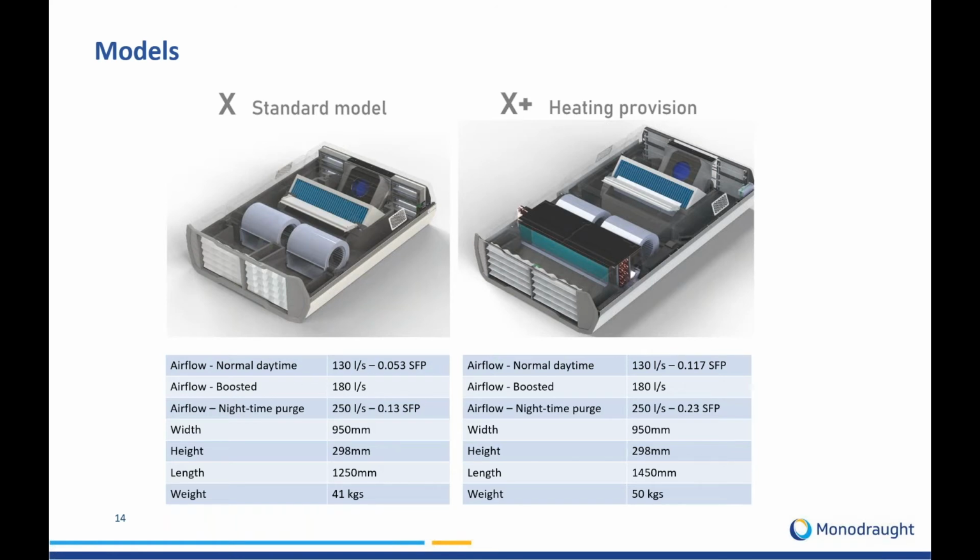The calculations are there, but not quite. So worst case scenario, we just said, let's incorporate an extract fan from day one. The fan with the black square with the blue circle in the middle, that is the extract fan at the rear of the unit. We're running it quite slowly for that type of fan. However, what that allows us, particularly in education where there's a science classroom, is that we can meet negative pressure for science mode.